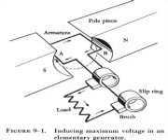Armature reaction current flowing through the armature sets up electromagnetic fields in the windings. These new fields tend to distort or bend the magnetic flux between the poles of the generator from a straight line path. Since armature current increases with load, the distortion becomes greater with an increase in load. This distortion of the magnetic field is called armature reaction and is illustrated in Figure 9-20: field excited, armature unexcited; armature excited, field unexcited; and both field and armature excited.